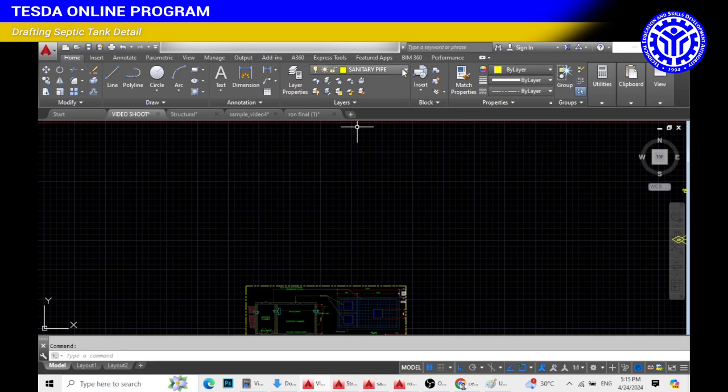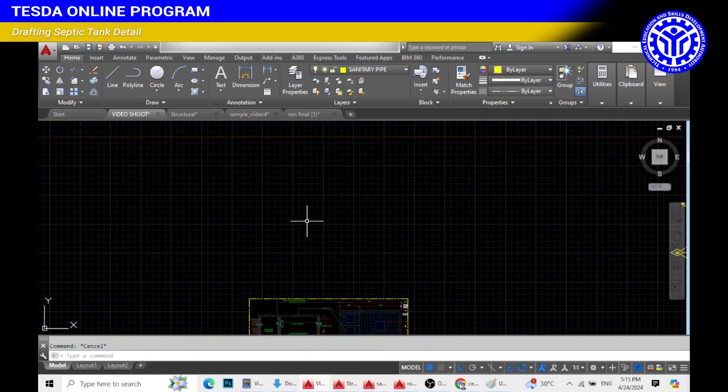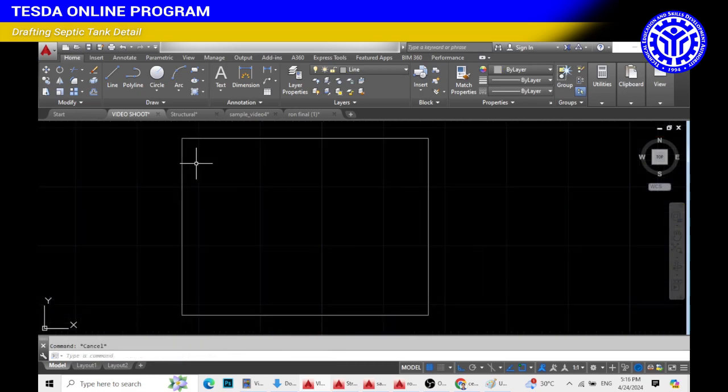From the Layer Properties Manager, select the line layer. Using the Rectangle command, create the septic tank outline using the dimensions provided. Using the Offset command, offset the septic outline by 0.1 meters.